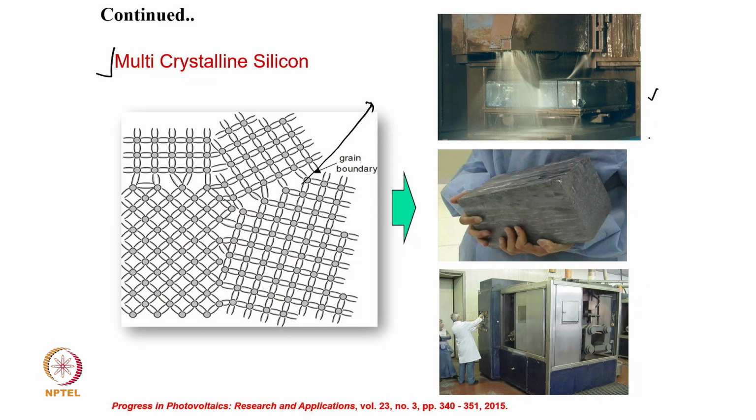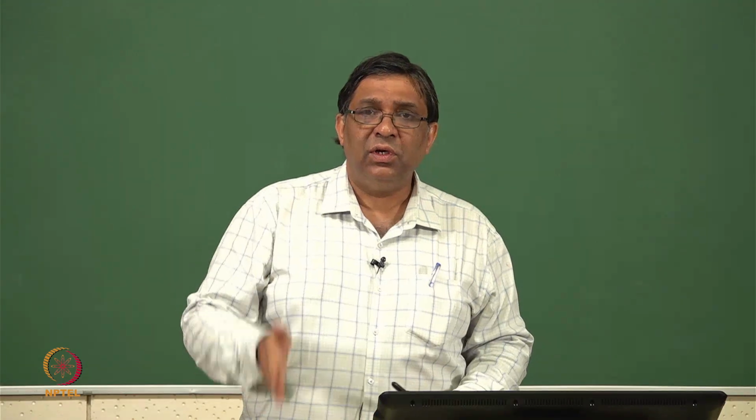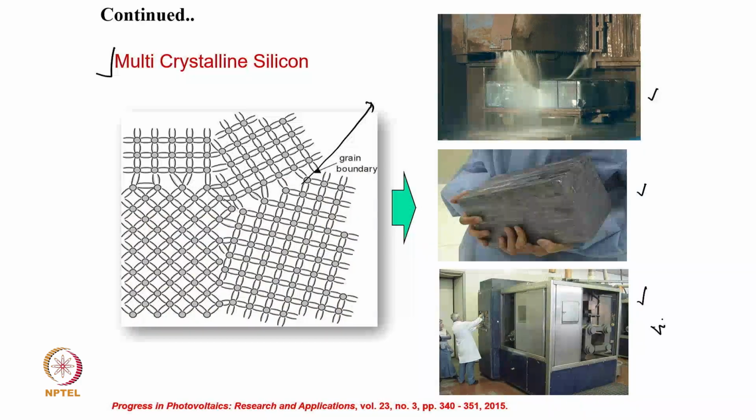So these are the typical techniques which people use in technology. When one makes a huge silicon polycrystalline ingot, you can see it starts from this. When you start processing from sand in your journey to a silicon wafer, you start with a huge, large ingot, and then you make bricks of multicrystalline silicon, and then in the third stage you have to cut them, slice them into wafers.